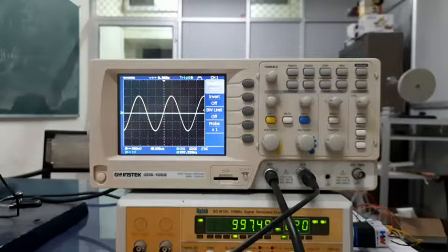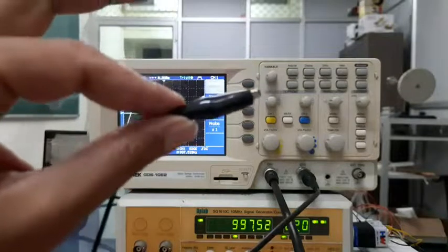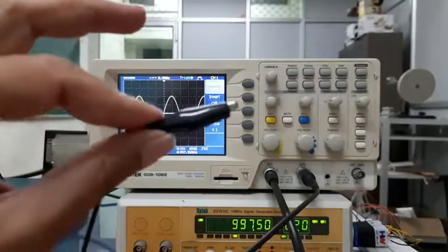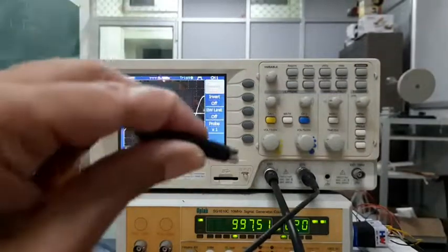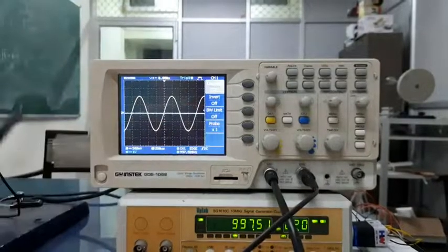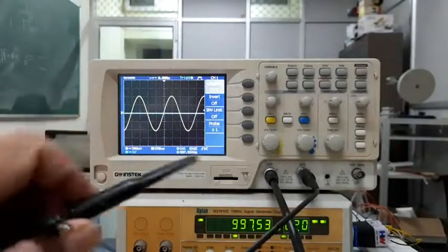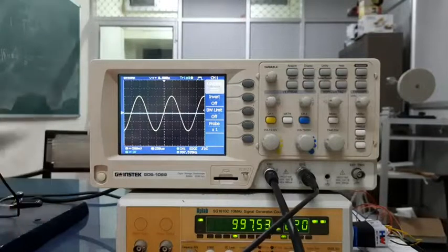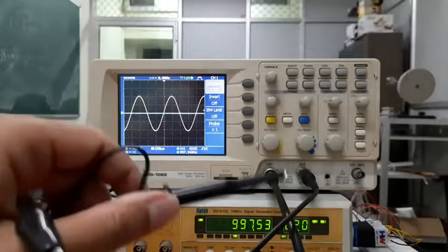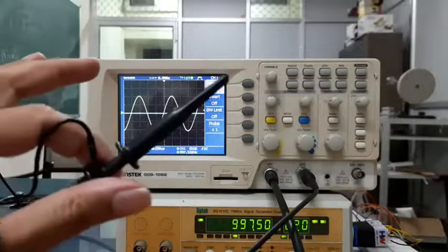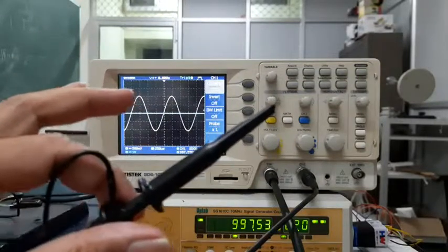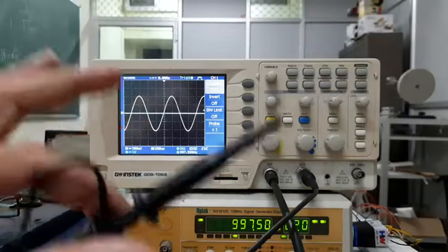So you can never pass a signal through this pin. So if you reverse the connections on the breadboard, if you connect your signal to this crocodile pin and ground through this hook, then you will not see the signal. So keep in mind that oscilloscope measurements on the breadboard use this cable, no other cable. You may have other cables in the box, don't worry about them.